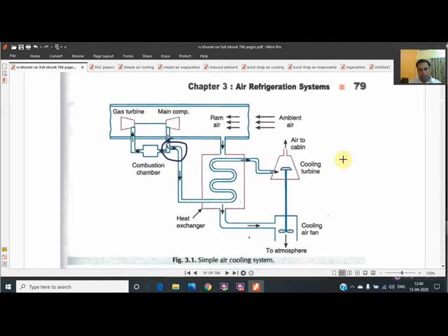For this, what we used to do, we used to calculate the refrigerative effect by two methods. One is from the question itself, that how much refrigeration is being done, m_a, mass of air, C_p, and delta T, because at the last the air used to go to the passenger and it used to get heated up.